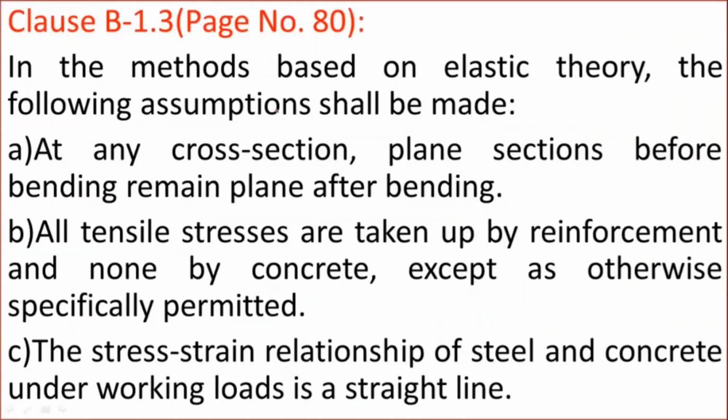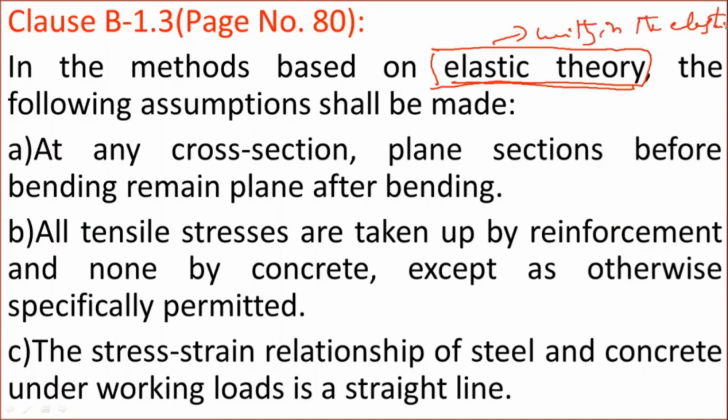So let us see the assumptions of the working stress method. So totally there are 4 assumptions. And remember that working stress method is based on the elastic theory. Elastic theory in the sense, whatever the loads are applied here, they are applied within the elastic limit.